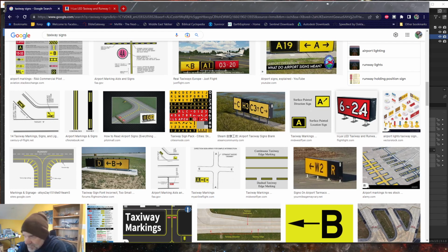And then you might want to set the min size of the LOD00 to something like 200%. If you remember, the min size for a level of detail is the percentage that the bounding box or sphere of an object takes up on the screen. So if you really want a highly detailed sign, but you don't want it to show up until the pilots are right up on it, you would set that min size to some large number like 200.